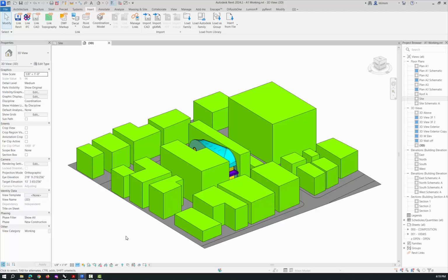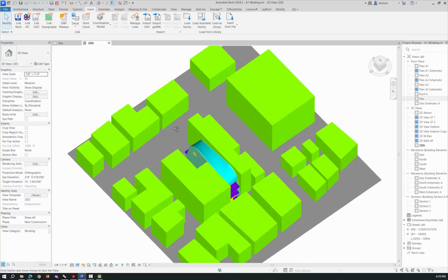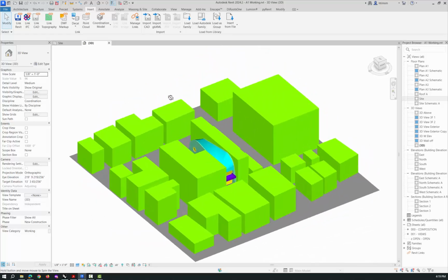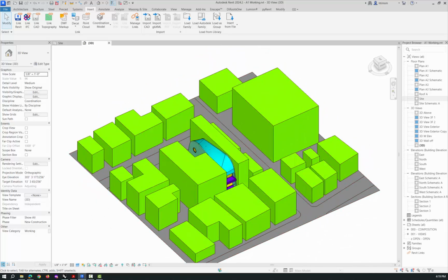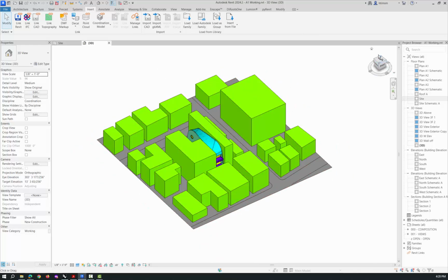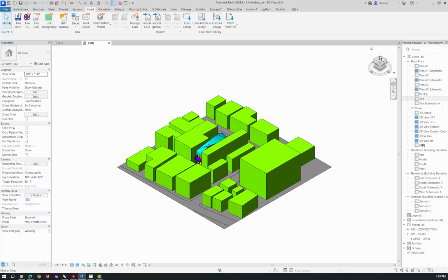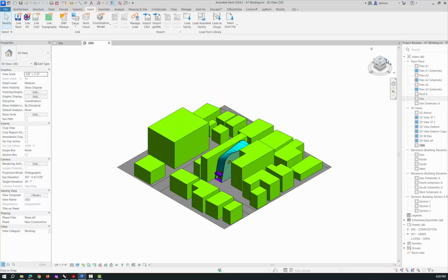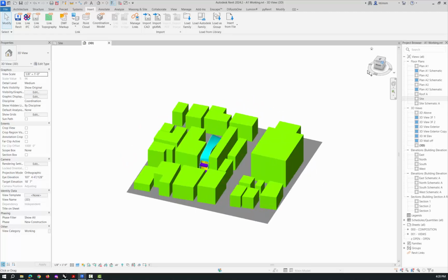If you have materials on it in Rhino, it will not come through. But basically, it brought everything in, all of the masses and the model and everything like that. So it looks pretty good. What I'll usually do at this point is just make sure that everything came in. If you're in your default 3D view, you have this little view cube over here, so you can spin around and look at this guy by clicking on the corners of it. It'll just spin the thing around for you.